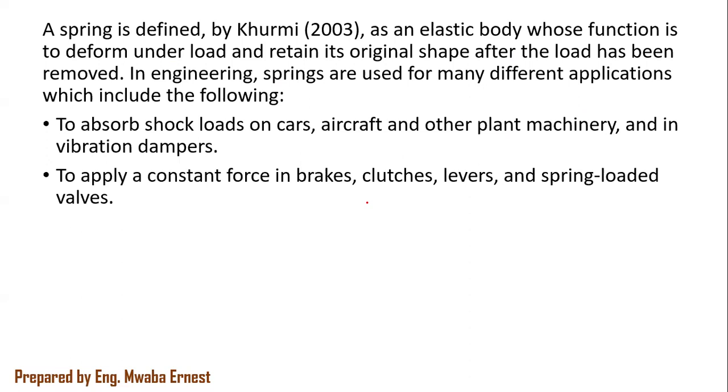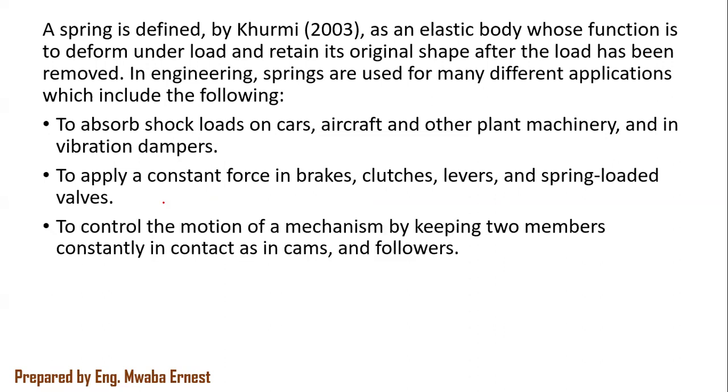Also, you have mechanisms like brakes, clutches, levers, and spring-loaded valves that make use of the same springs. So when you apply brakes, a part behind there's a cylinder, and then there's a spring which is already sitting there, such that when the fluid pressure goes away, the spring return pushes the piston in its place. Different mechanisms, different arrangements, but all making use of the springs.